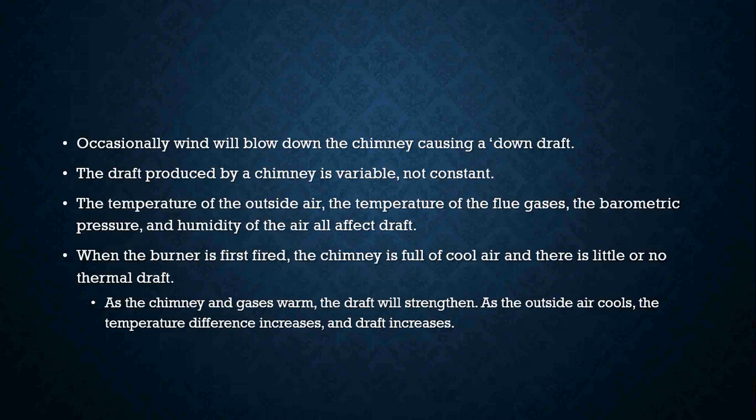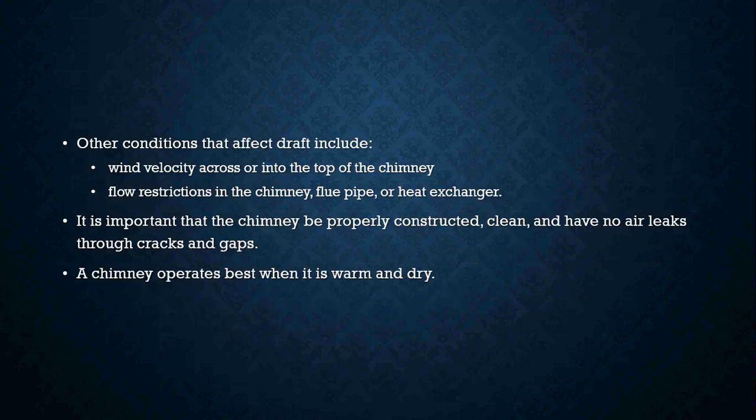So when the burner is first fired, the chimney is going to be cold. It's going to be full of cold air, and therefore little or no thermal draft is going to be taking place. So as that chimney and gases warm up, the draft will then strengthen. As the outside air cools, the temperature difference increases, so therefore your draft is also going to increase.